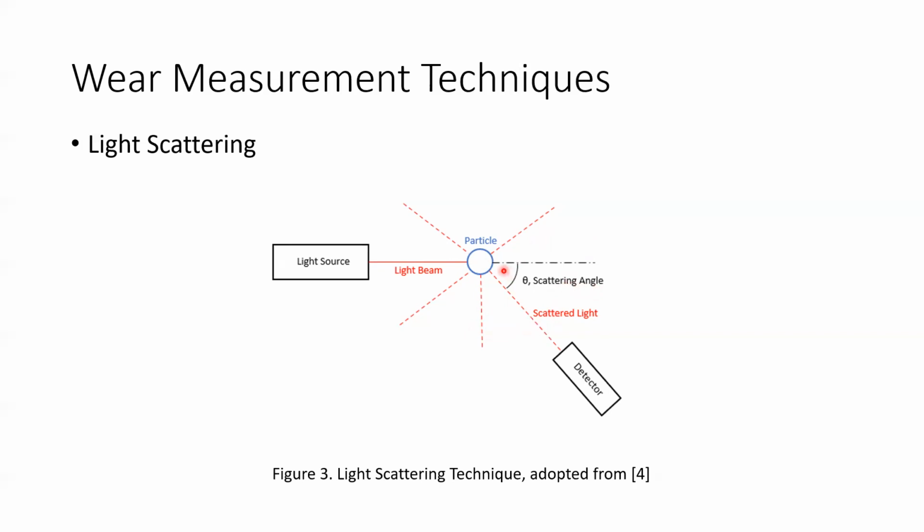For example, when a small particle is placed here, light intensity is more uniform at these different angles, while a larger particle causes a larger variation of light intensity at different angles. Therefore, particle size and concentration information can be obtained with this method. This method also makes continuous measurement possible.